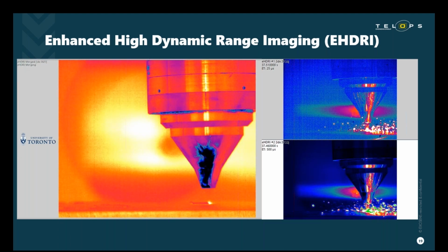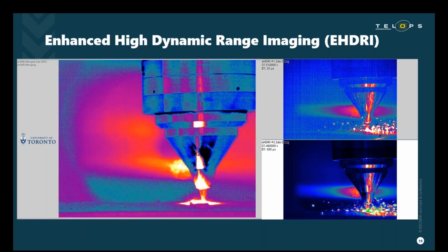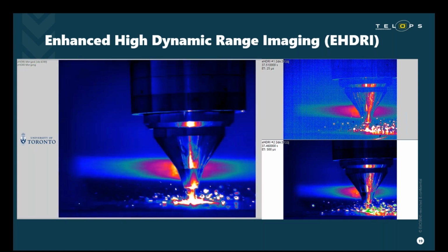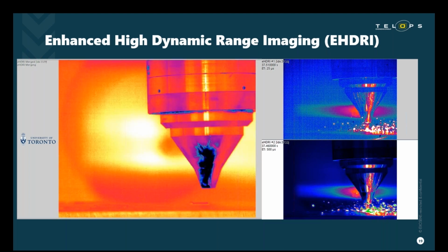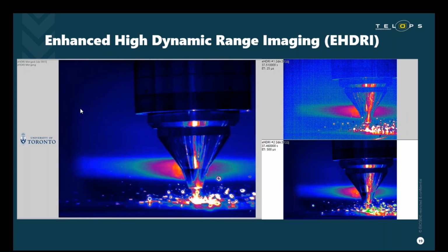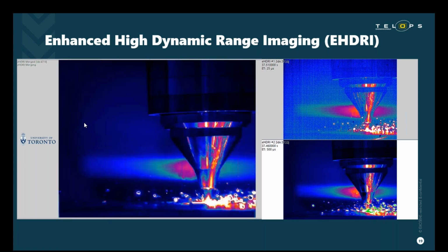And we also set a high exposure time around 500 microseconds. We were able to see the laser head and the background without all of the noise that you see there in the lower exposure time image. So recombining, we have this beautiful crisp image where we're able to see good detail and have radiometric accuracy in both the high and low temperature portions of our scene.